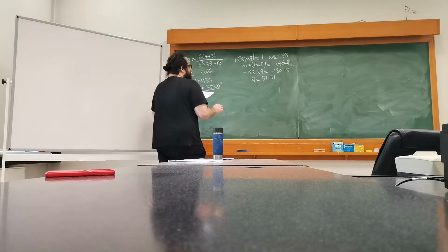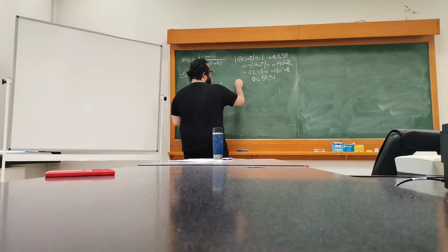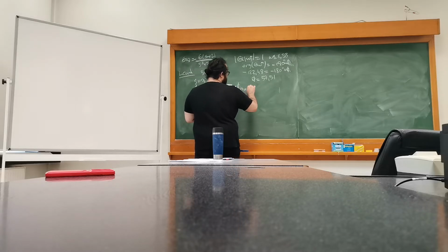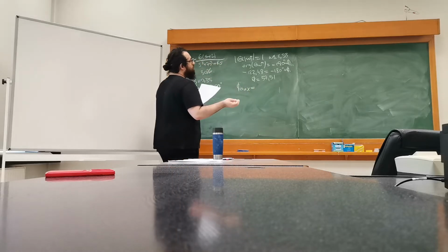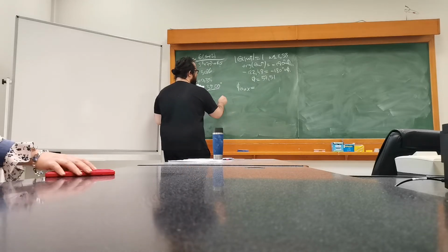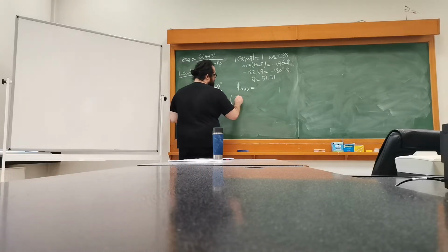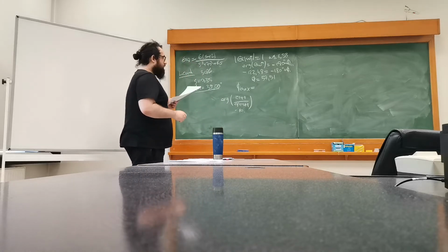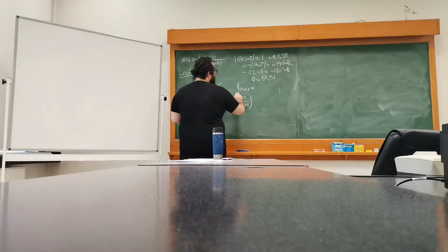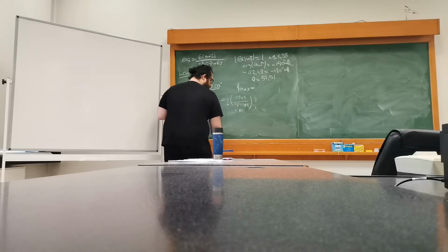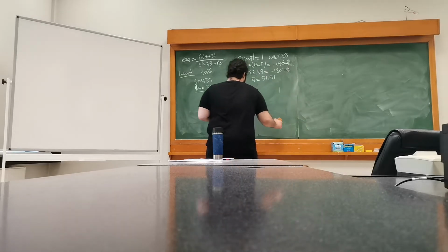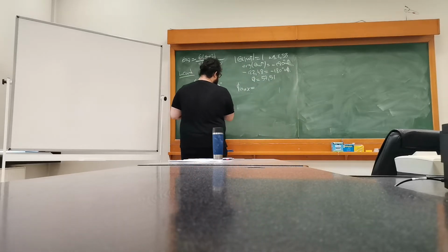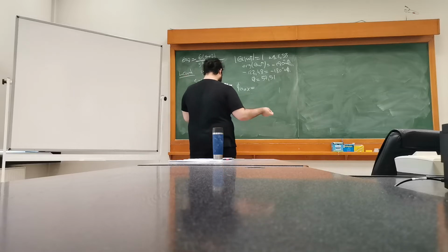Now we have something called phi max. As it was the case for the lag controller, where we had the argument of tau s plus 1 over alpha tau s plus 1, and we assumed that this will be less than or equal to minus 10, we have the assumption that the dynamic part will have phi max as its maximum value. So we are going to look up or calculate that.